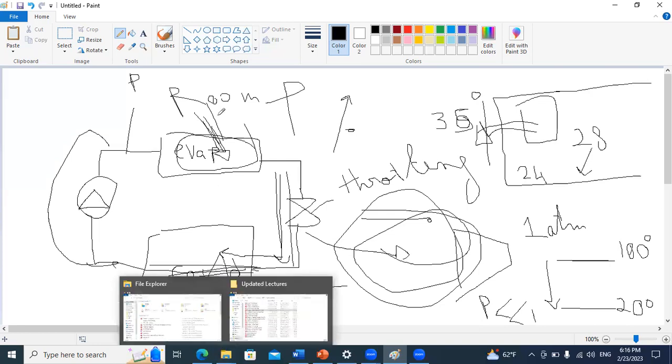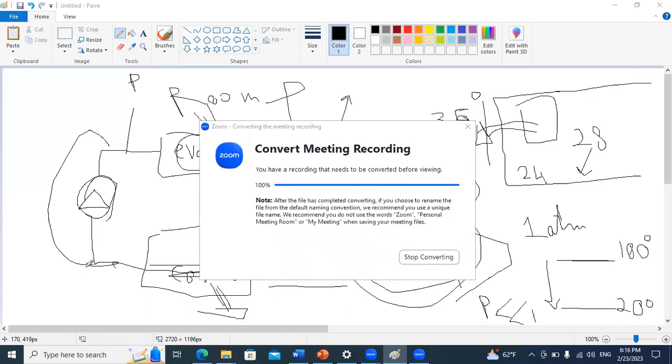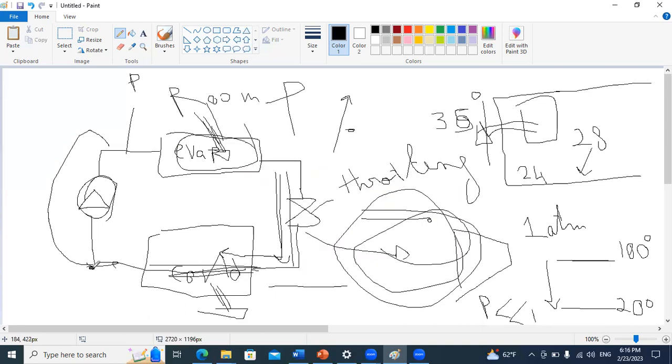And in general, in the evaporator and condenser, we have a mixture, we have two phases. This is why we'll introduce in this chapter how we deal with phase change, how to get properties during phase change. Now, whenever I exit my condenser, the pump is here to allow me to repeat the cycle, because it will allow me to go from the low pressure at the exit of the condenser to a high pressure at the inlet of my evaporator. And this cycle will be repeated.